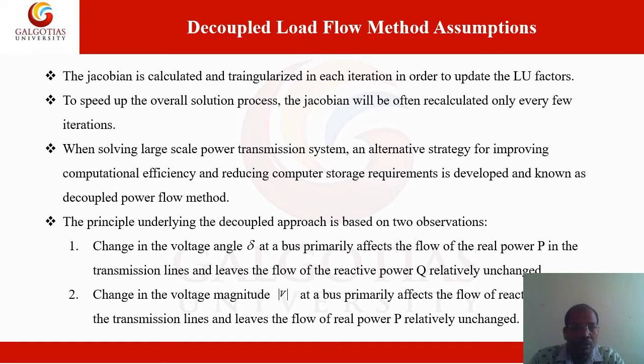Using these two assumptions, we can decouple them and solve these two correction factors separately. That is why it is called the decoupled load flow method. Using the decoupled approach, we can speed up the overall computational efficiency and reduce the storage problem in the Newton-Raphson method.